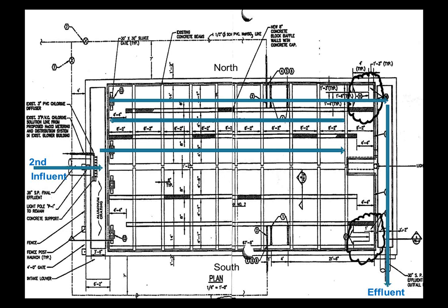It's a little busy, but I'll kind of guide you through it. The secondary effluent comes in from a single pipe from 3 clarifiers, hits a head wall, splits off, and immediately goes into 2 channels down to the end. It's a typical serpentine, goes back, and finally goes to the far end, discharges through a weir, and directly to the Ohio River. It's about a 25-foot discharge line that goes to the river, and I'll show you what the flume looks like going to the river.